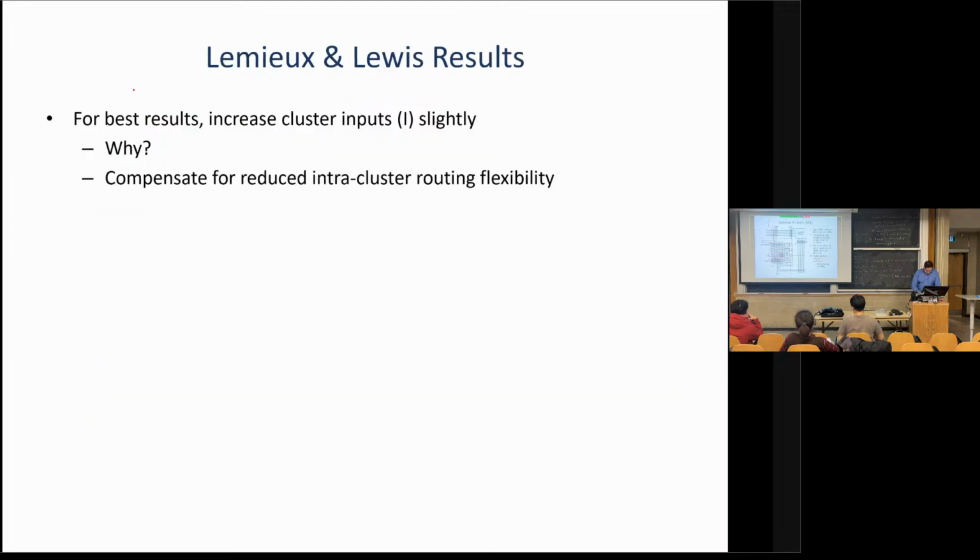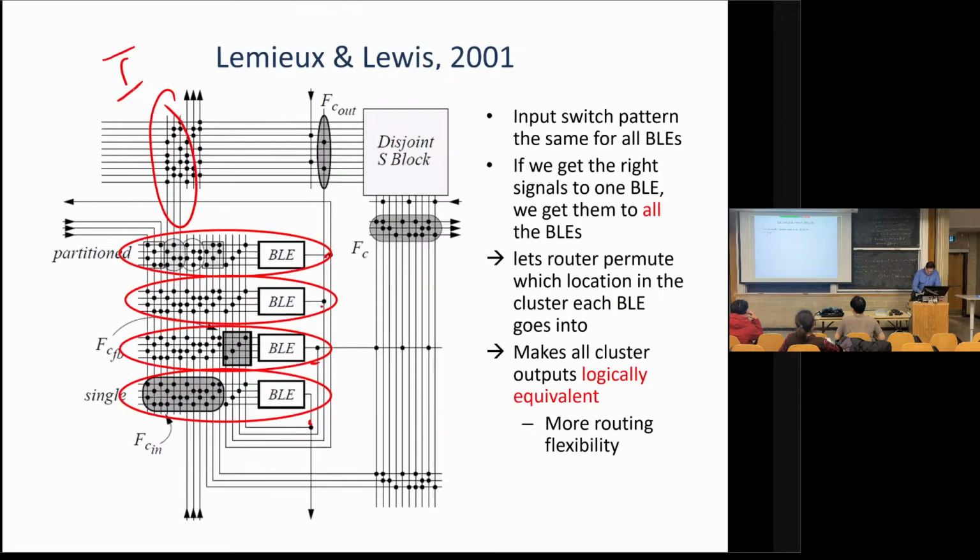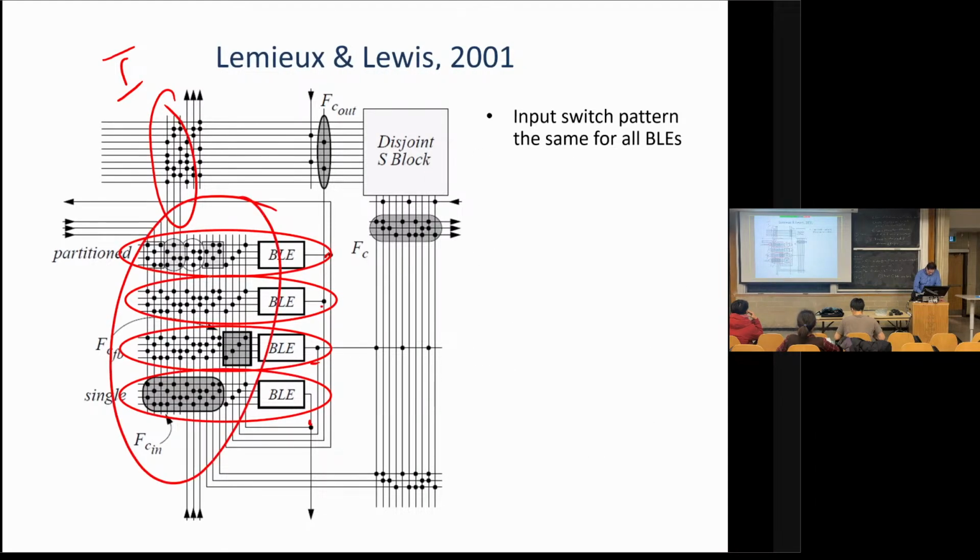So it basically comes from I've taken a bunch of flexibility away from here, and I saved a bunch of area for doing that. So it was a pretty good idea, but routing has gotten harder. If I add a little bit more flexibility by having more inputs coming in, I basically reduce the probability of routing blockage. Especially because the cluster in VPR was still allowed to use, like if I had 30 inputs, it might sometimes use all 30 inputs. If I saturate the inputs to this thing, the probability of getting blocked when I've removed some switches in here becomes much higher.